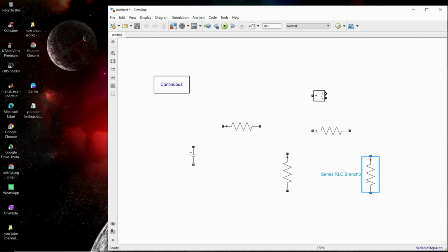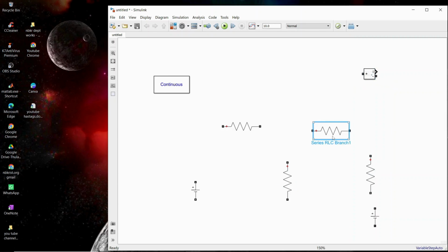you get it in vertical. And you require one more voltage source. Copy this voltage source and paste this voltage source. Now we require the current in all the branches, and at the top also you have one more resistance. So copy this resistor and paste here. So this is a bridged network. Now we have to inject the ammeters also in each branch.